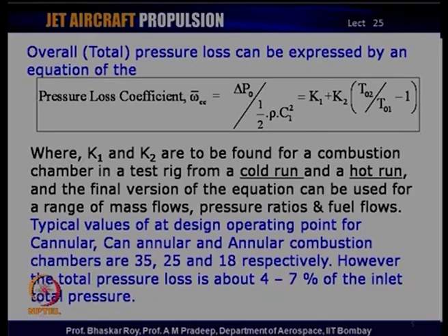And for a given combustion chamber geometry, once a certain geometry has been decided upon, this can be taken to a test rig and certain runs or test rig performances can be measured, and these two parameters can be quantified. And then they can be put in the equation as given here, and can be used across a large number of mass flows and pressure ratios and fuel flows.